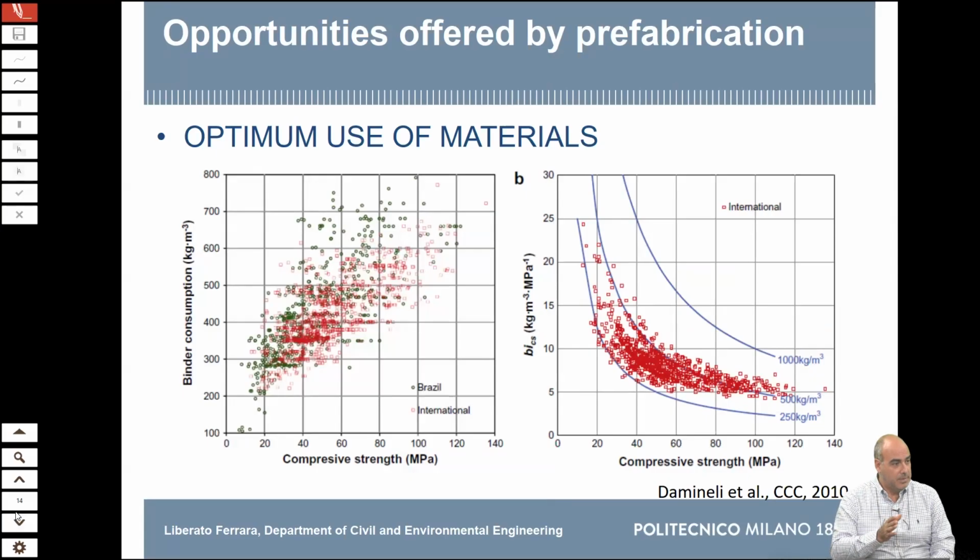It's true that if you want a better strength concrete, you must use, among the mix design characteristics, a higher binder content. You cannot have a better strength concrete without using a higher binder. But it's not the only thing. To have a higher strength concrete, you also use different mix design methodologies. You go to aggregate packing concepts, you use admixtures and so on.